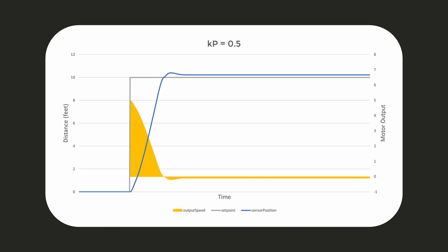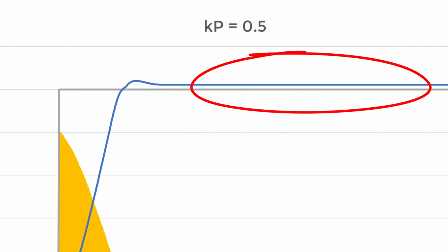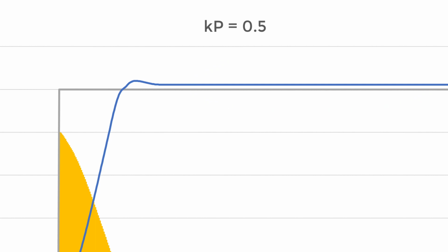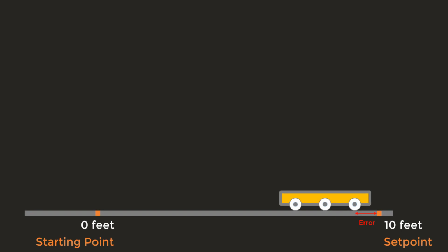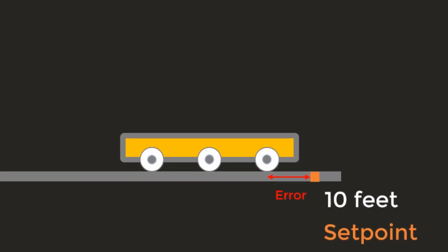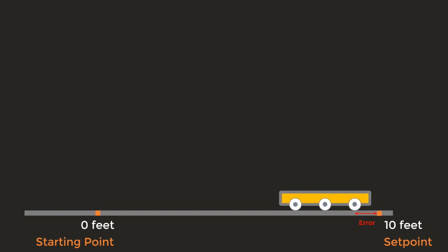Great! The general motion of the slowing down is achieved. However, the problem with only proportional control is that it could be inaccurate. As you have seen, the robot could still be a tiny bit away from our set point. In theory, if there's any error, proportional control should continue to adjust the robot's position. However, when the error is tiny, the generated output will be tiny, and it may not even be enough to overcome friction, therefore leaving the robot unmoved.